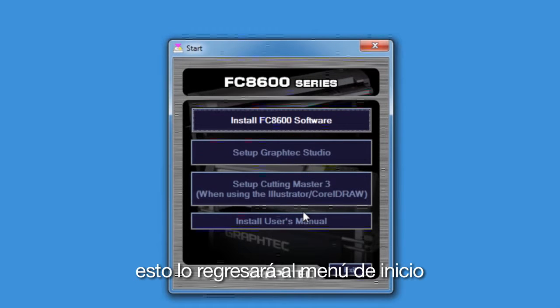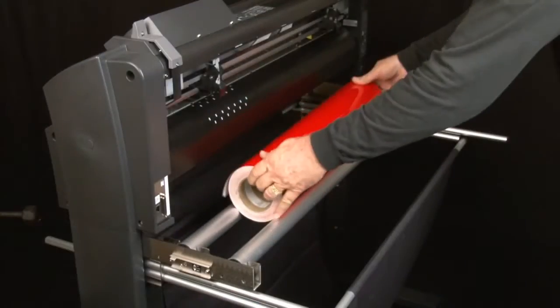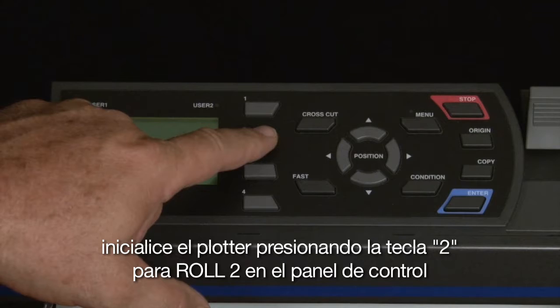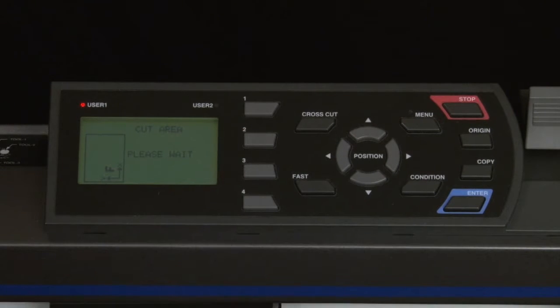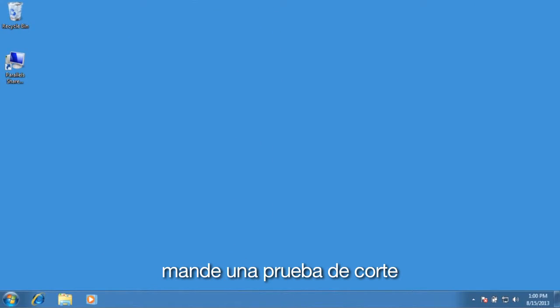This will bring us back to the main menu. Click Exit. Finally, turn the cutter back on and load the media. Initialize the cutter by pressing the 2 key for Roll 2 on the control panel of the cutter. To make sure that there's communication between the controller application and the cutter, let's send a test cut.